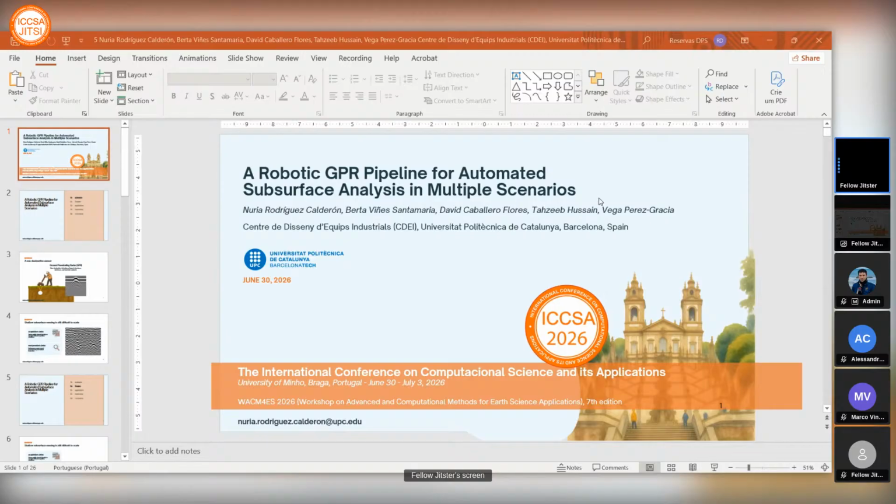But what we can see here is like the Fourier transform, and note that PI is peak instantaneous amplitude, which is a parameter of the radargrams, which is correlated, we would say, with the water content. These different colors mean the variation of the soil, because the soil doesn't have a homogeneous water content, so depending on the zone, it can have more or less. But in any case, we can see a strong positive correlation, and we are still investigating that further.